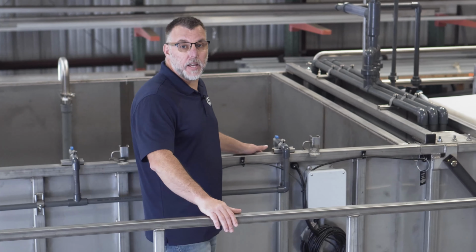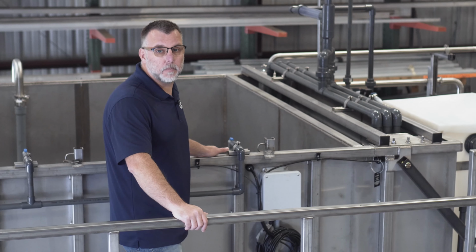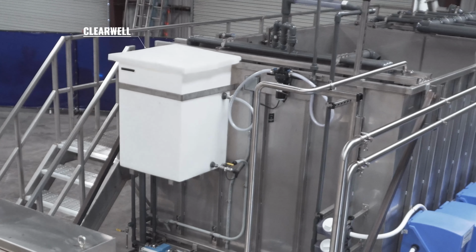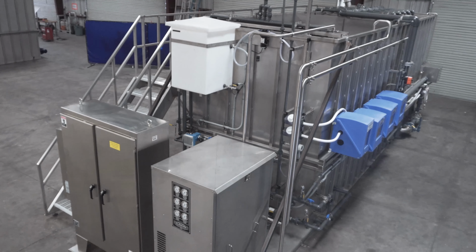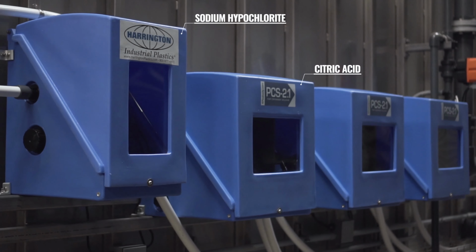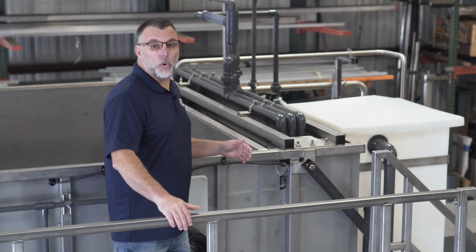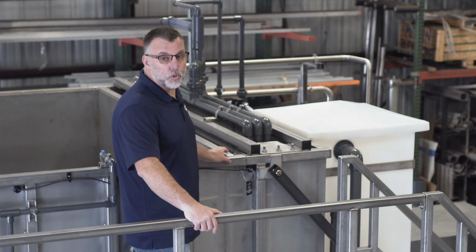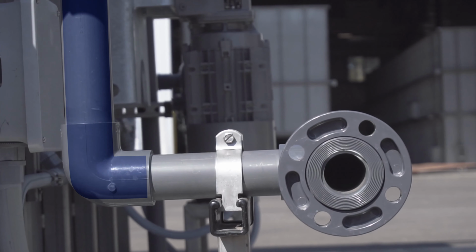The membrane cassette is cleaned automatically on a routine schedule set by the operator. Effluent stored in the clear well is pumped back through the membrane cassette, and the operator is allowed to select either sodium hypochlorite or citric acid to inject to clean the membrane surface and interior. During normal forward flow operation, treated effluent will flow from the clear well to sanitary sewer disposal.